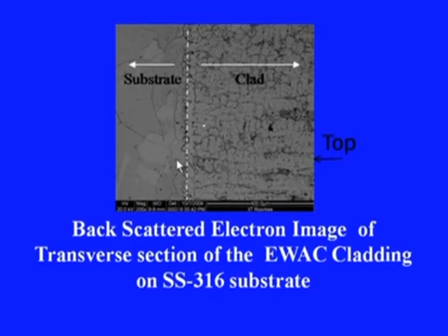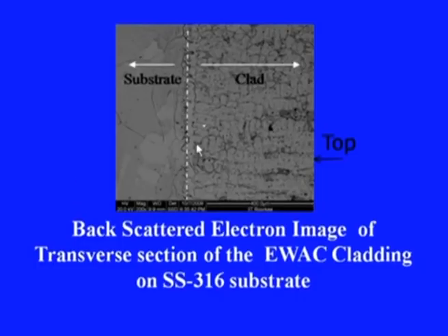There is no mechanical bonding, as exists in the case of coating, which is why coatings become a little weak. But here the clad appears to be an integral part of the substrate material itself, although there will be a little property difference between them as the cladding material is different.